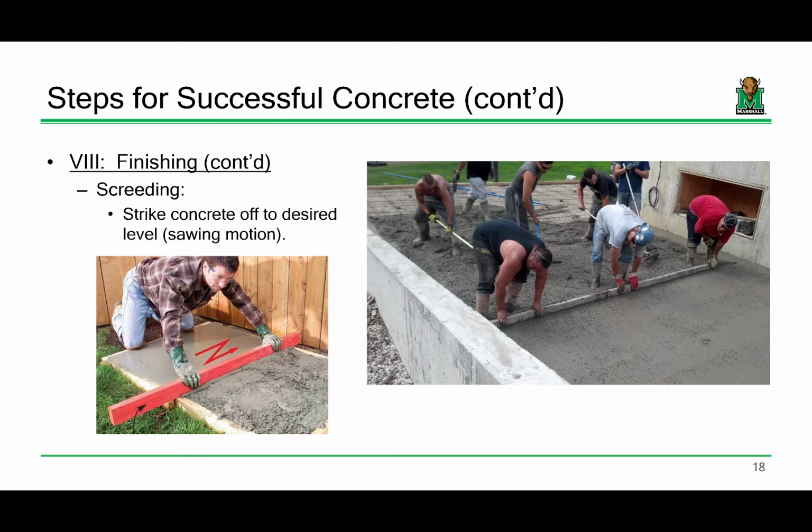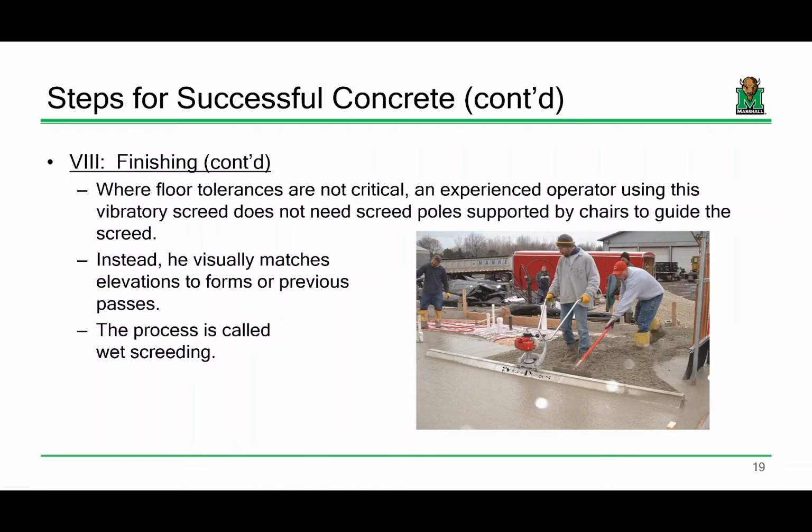Now, that process is called screeding, okay? So in the case of the sidewalk, the little pad in your backyard, the large patio placement and whatnot, the most common way of doing that is to use some scrap lumber, like a 2x4, okay? Essentially what you'll do is take it, and I found that the easiest way is to sort of zigzag it, right? If you've ever, how many have ever done this before? I'm just curious. Zigzagging is the way to go, right? So you take it, you just sort of do that to get your near surface, and then you'll smooth it out with a trowel or something like that after, okay?